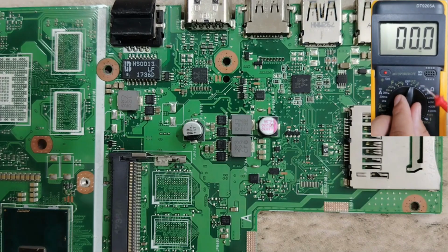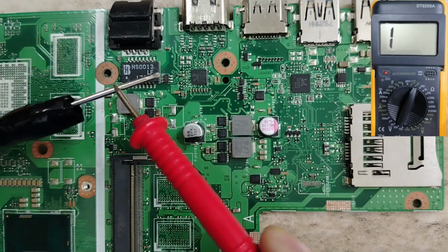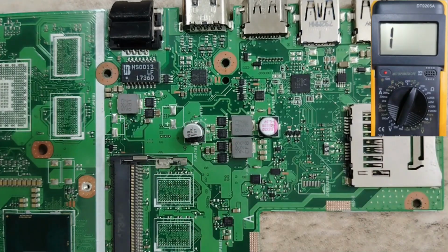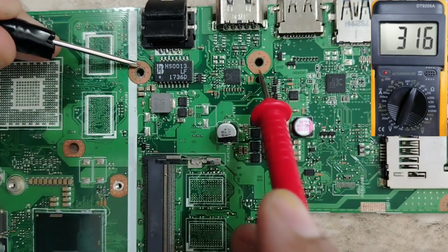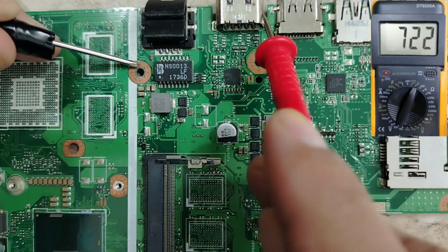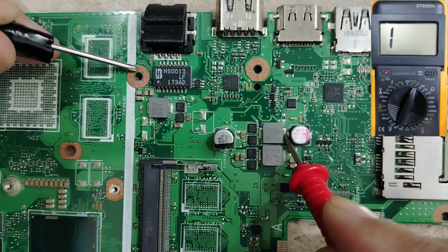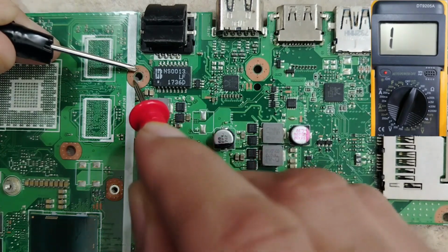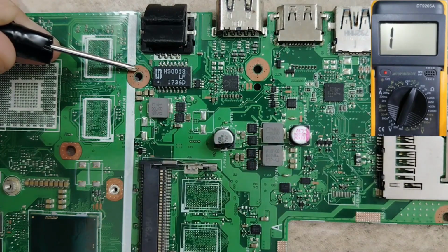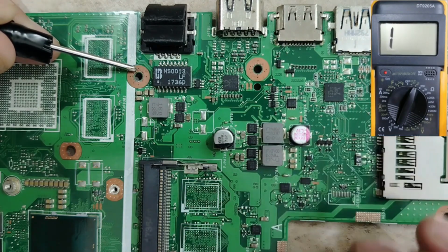We can even check using the multimeter. So let's select the continuity option here, as you can see. Let's check that the multimeter is set correctly. Go to the continuity option. If we put, for example, one probe here on ground, here we have ground, here ground, here ground, everywhere is ground on the motherboard. If we check this inductor, do you see? You can never find a direct continuity between an inductor and ground, because the inductor can never be connected to the ground in a laptop motherboard.